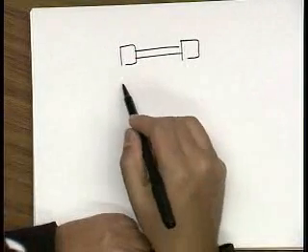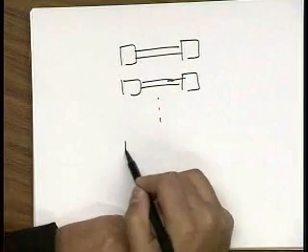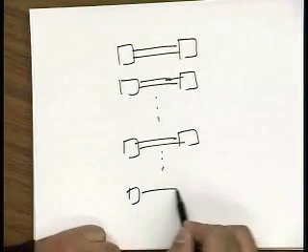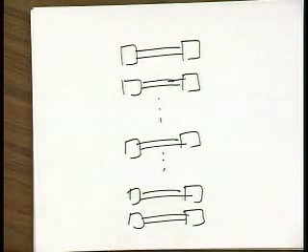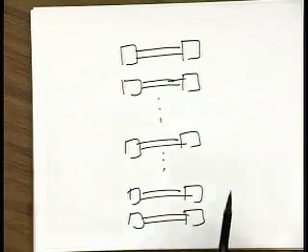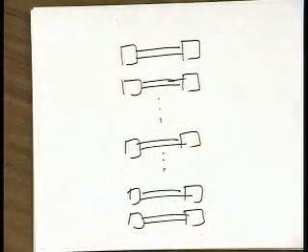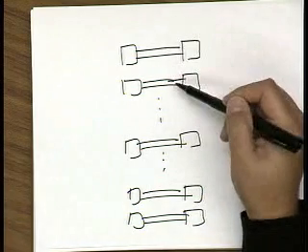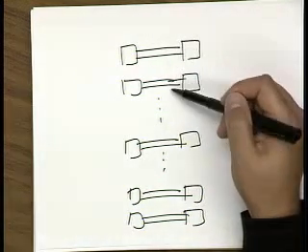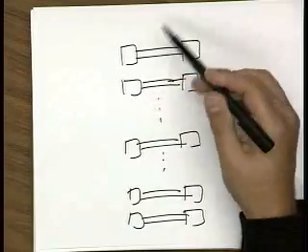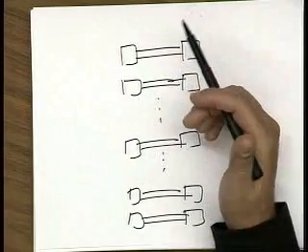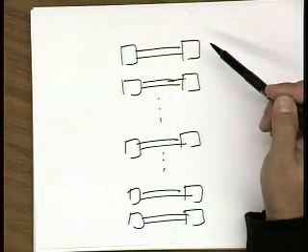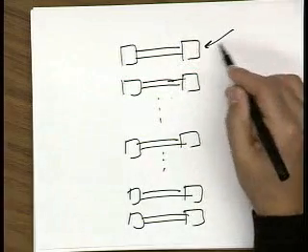Okay, so the idea is that when you're doing unit cell designs, you're going to do an array of devices. And what you want to guarantee is that any particular sub-device sees the same, let's say, environment as much as possible as the rest of the sub-elements. In that way, you guarantee that they're going to be matched as well as possible. So for this guy at the end, there is a big discontinuity. The guy at the end, on one end sees a resistor. On the other end, it sees, let's say, nothing, or maybe some other device that you've placed there. So you've already introduced a systematic error into your design, because you're going to have end effects.